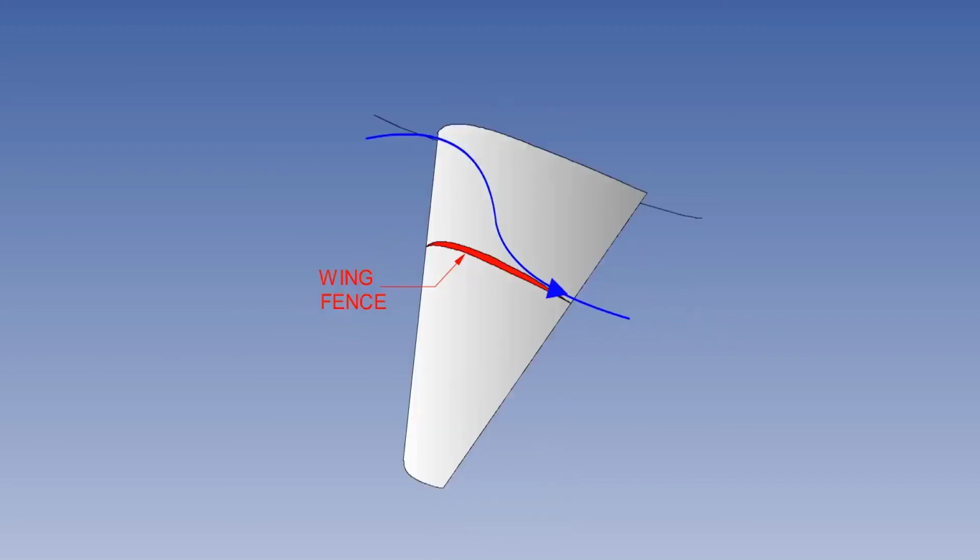The tendency of a swept back wing to tip stall is due to the induced spanwise flow of the boundary layer from root to tip, and there are several design features that can be incorporated to redress this effect to give more acceptable stall properties. Wing fences are thin, upright metal strips which generally extend from leading to trailing edge and restrict the outward drift of the boundary layer.